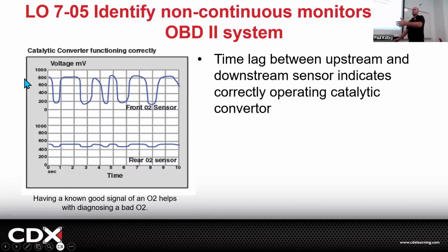If you were to use your meter, you'd see the meter say 800. And then it would go boop, boop, boop, to 200 and then boop, to 800. But you can't really get an image of what the voltage is doing. So this graphs it for you. This graphs it and kind of records it, right? So we're looking at a waveform here. This one here is a little sloppy, but this is a reasonably good oxygen sensor reading. But can I trust it? I don't really know. If it doesn't set a code, I'm pretty happy.